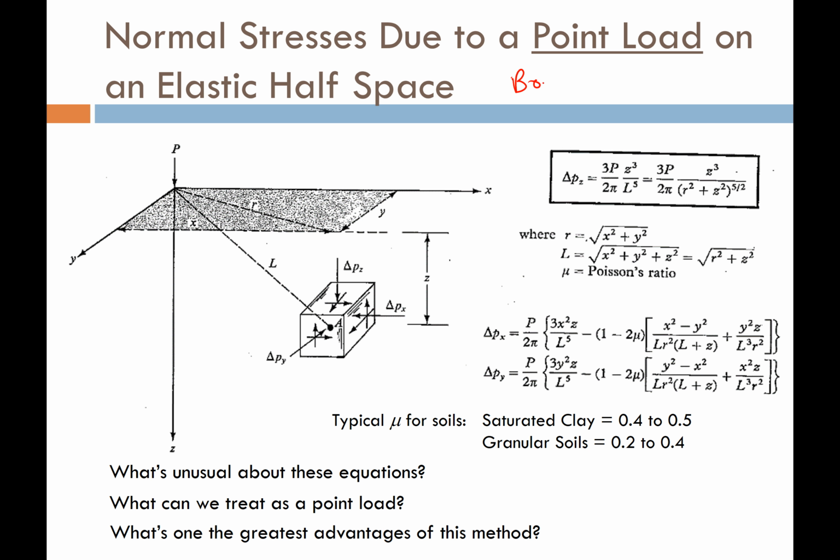Let's look at the Boussinesq solutions. Boussinesq was a French engineer, and using elastic methods derived a whole series of equations that would give us stresses or induced stresses in the y, in the x, and in the z direction on a soil element from different types of loads placed on the ground surface. Now, this particular solution I'm showing you is for a point load.